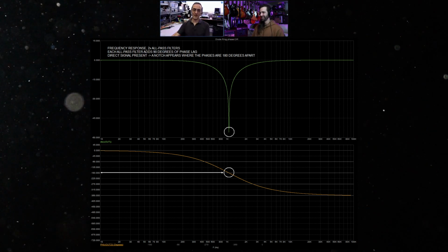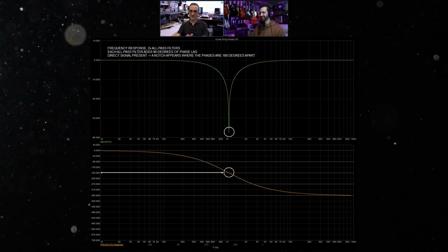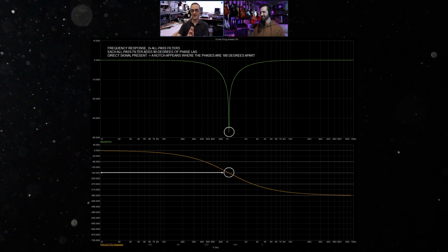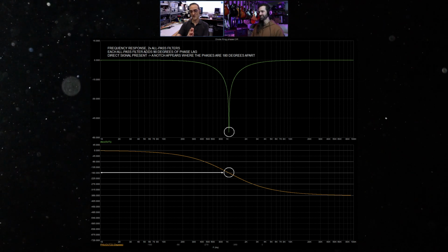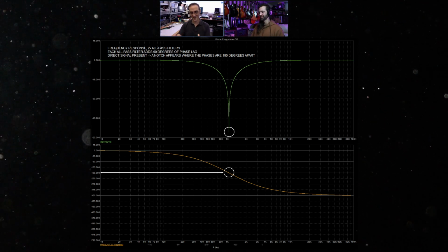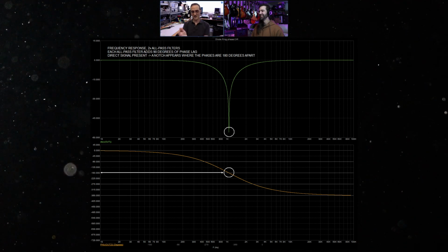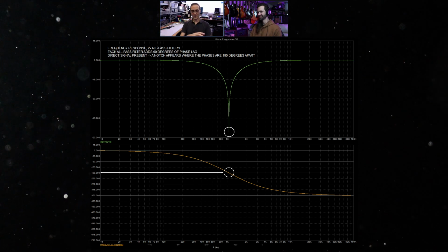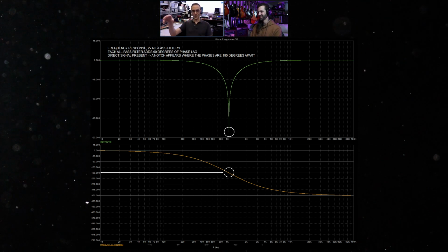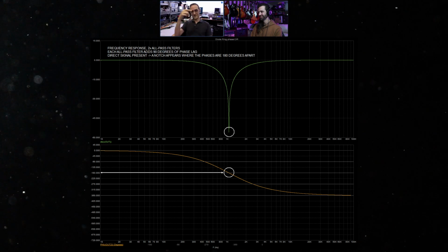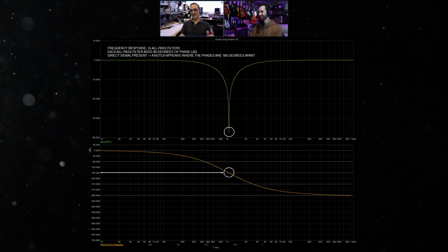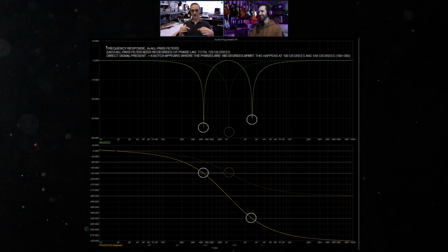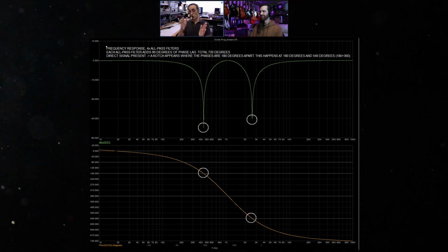Okay, so now the trick is that this filter doesn't have enough phase shift. So that's why you have phasers with phase 90. Okay, it's 90 degrees of phase, so you get your signal 90 degrees out of phase. You start putting in more stages, like 2, 4, so the number of times the signal's phase is changed is higher. So you get more notches.